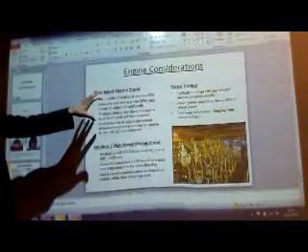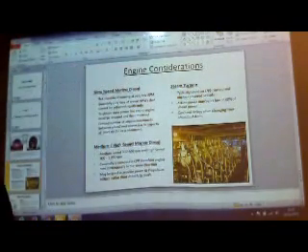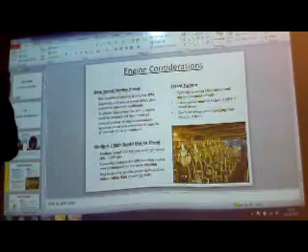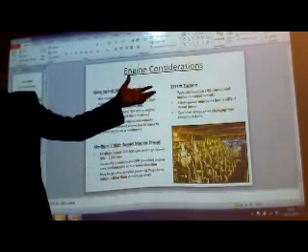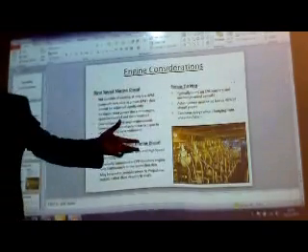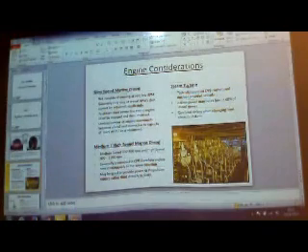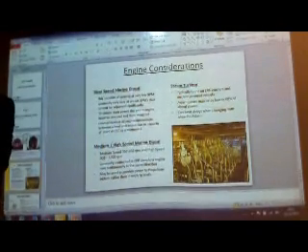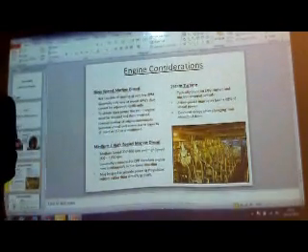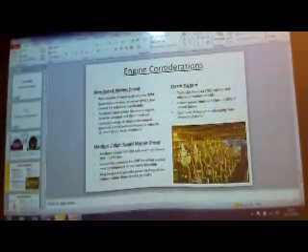So that would be that kind of a ship. A bigger LNG ship which is moving 200,000 CBM of LNG in bulk from one continent to the other would have a slow speed engine, maybe RPM of 80, 90 or 100. One very big propeller. It will then slowly keep on turning and keep on turning. But then it will have limited maneuverability, because to create maneuverability you need smaller propulsion systems specifically placed, running at higher RPM so that they can move about more and achieve higher maneuverability. Makes sense to you? Yes.